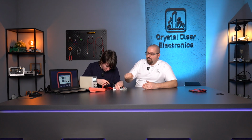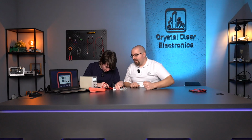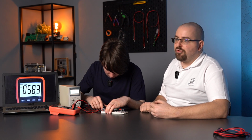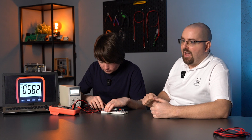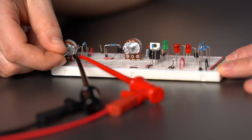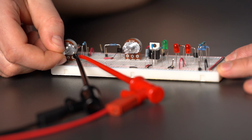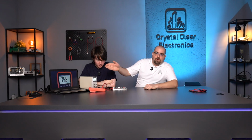I will show you here that the R2 load would be this potentiometer. It has a resistance of 10 kΩ and now we're testing the circuit in a no-load condition. That means that I'm now turning it to the 10 kΩ position, so that's a very tiny current flowing through it. So you could say that there's no load on. You can clearly see the current consumption. Marci, can you read us what you see on the multimeter? That's 5.8 milliamperes, which is what we calculated.